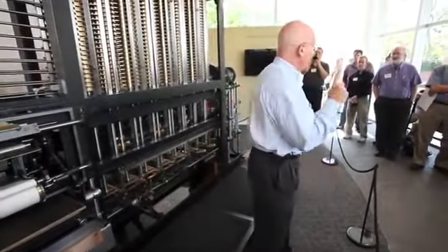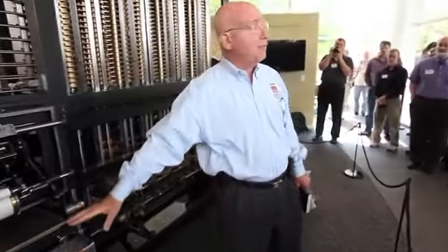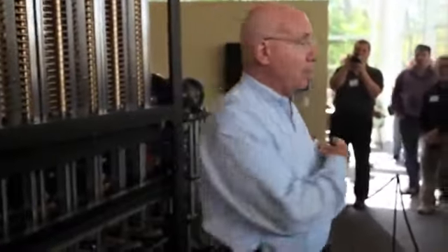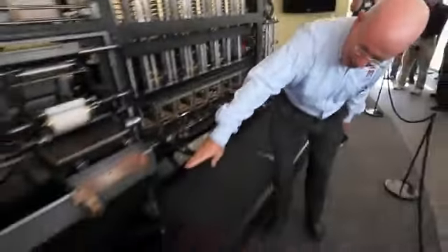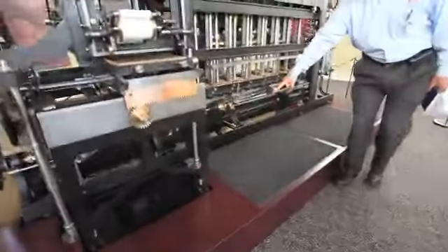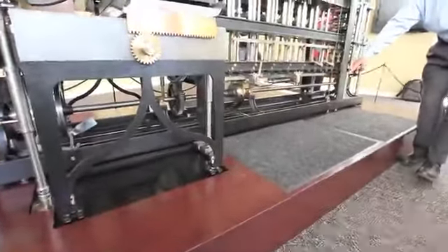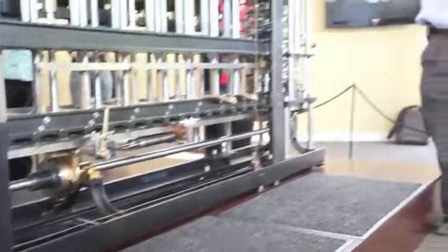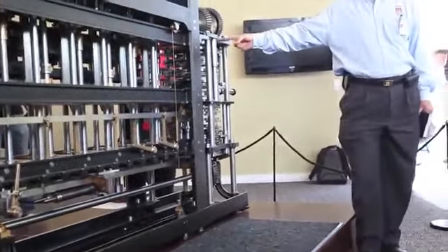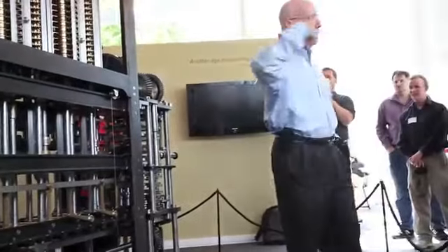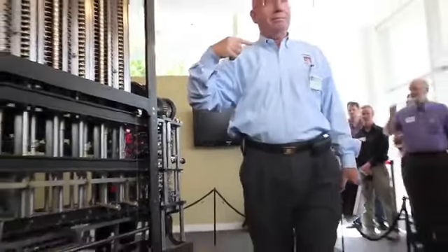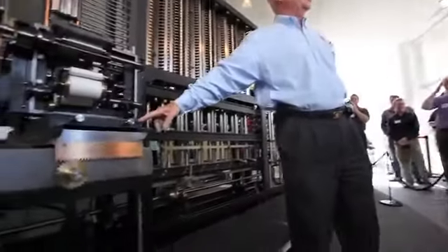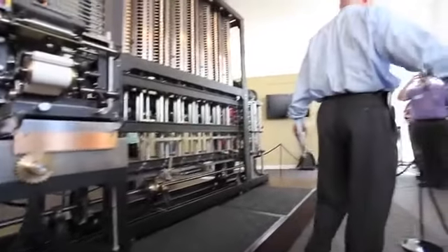In addition, what happens when this tray is full? Julie's way down here. You don't want to overflow this thing, right? So there's a little weight dropping down here, which is pulling on this piece of catgut, which comes up here, across the machine to a little pawl. When that tray fills up, it's going to shut off the machine by disconnecting the crank. That means you've got to come down here and change this tray. We thought of all these things.